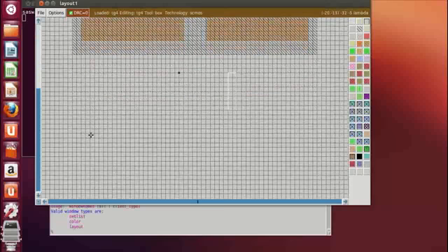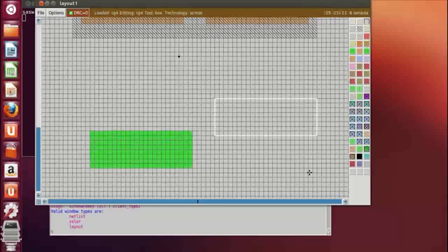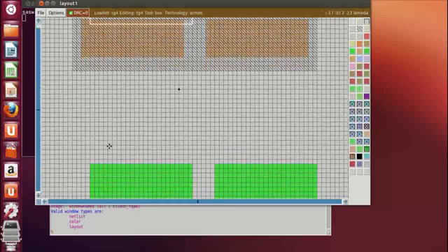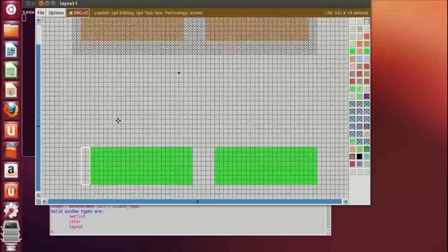Now here below this we have the end diffusion layer. So select the portion and then middle click on the end diffusion. Similarly over here, select the portion and end diffusion. Okay, so now we have to short these two. Okay, we need some more. Even I don't need to go here and press the middle button on my keyboard. I can directly press over here. If I press the middle key of the cursor over here also, I'll get it.